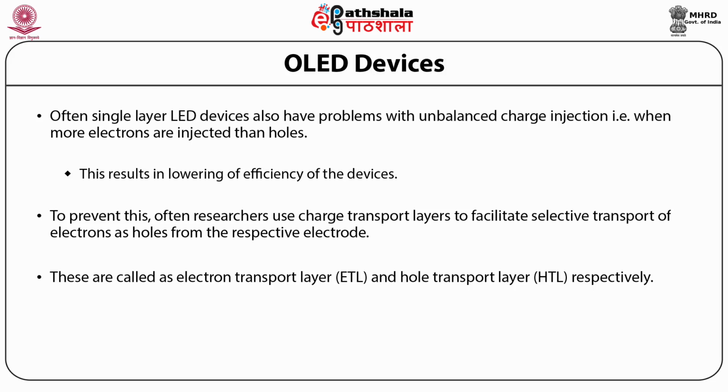First, if there is an energy barrier between the electrode Fermi level and the HOMO or LUMO level of the emitting layer, these layers provide intermediate energy states, making transport of electrons or holes happen through smaller successive steps of energy barriers, improving the device performance and helping in achieving low voltage operation.